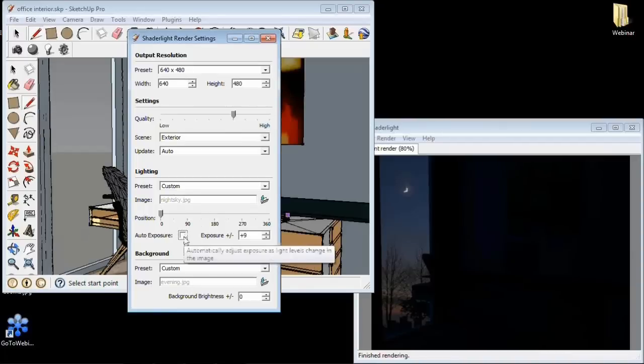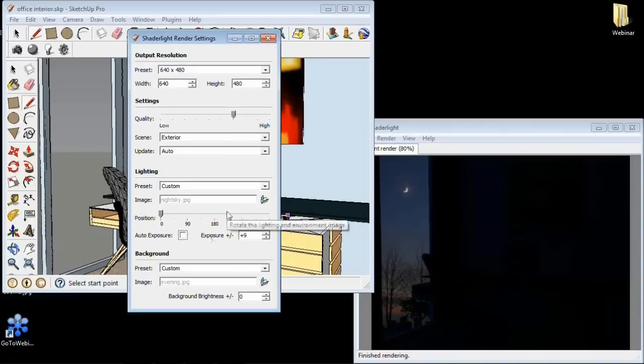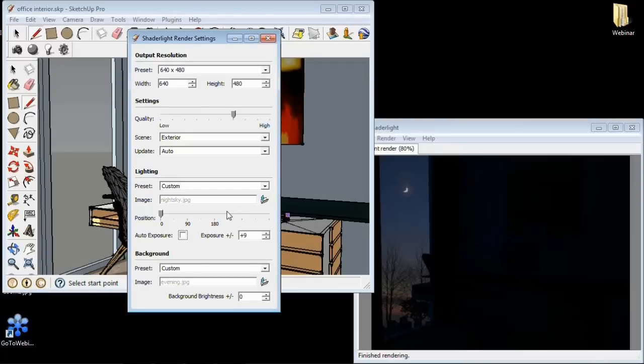The auto exposure is very useful because it creates that daytime environment, but it does also create some behavior that we get asked about a lot. Particularly if you put a light into a scene on a sunny day, people say, well, why can't I see the light? The reason is that it's like looking at a light bulb in the middle of a sunny field. You wouldn't actually see the light coming from it. So that's the reason why you're getting that.